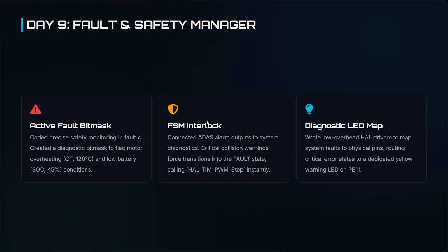If any of these boundaries are crossed, the diagnostic fault bit is set. The fault manager immediately overrides the system and forces the FSM to fault state, shuts down the motor drive, and illuminates a physical yellow diagnostic LED which is connected to pin B11.